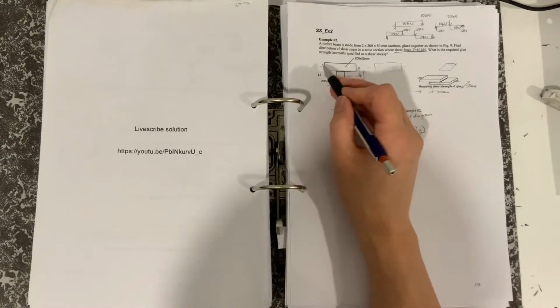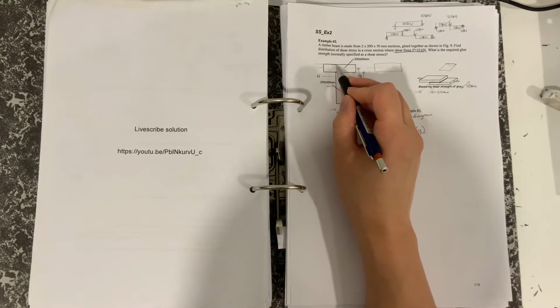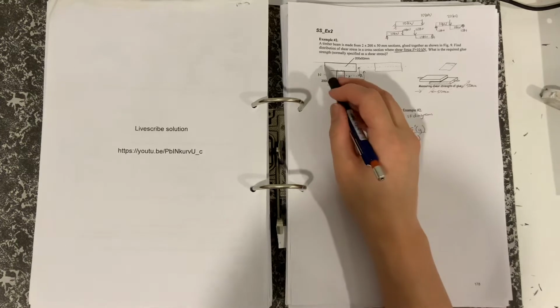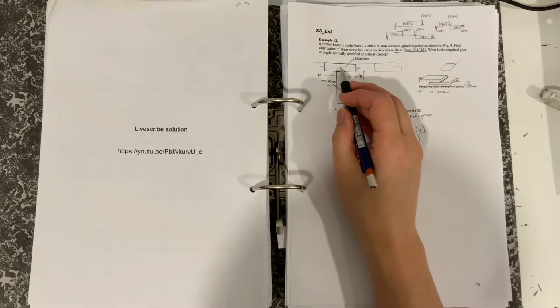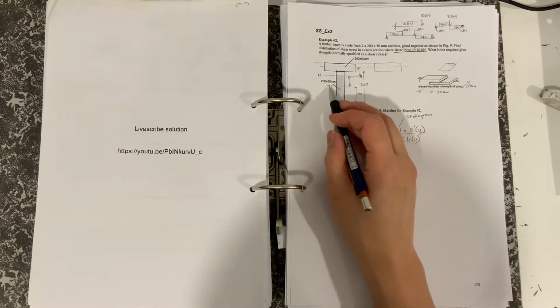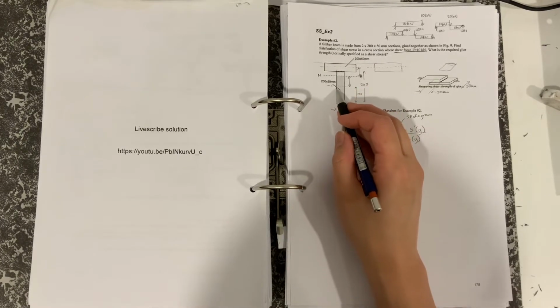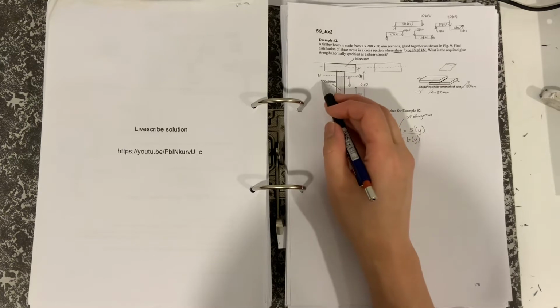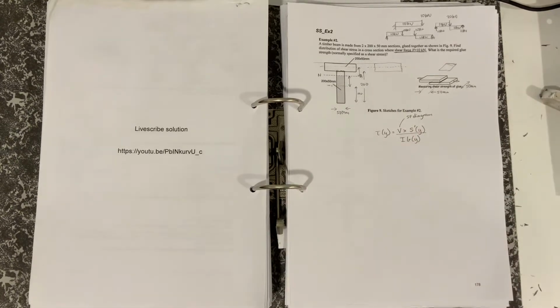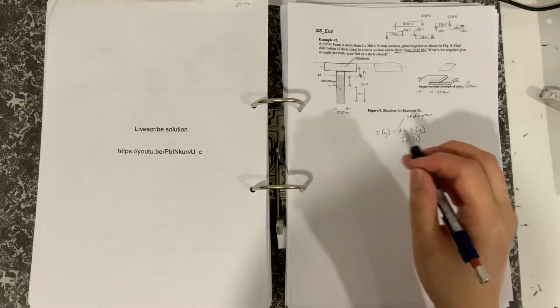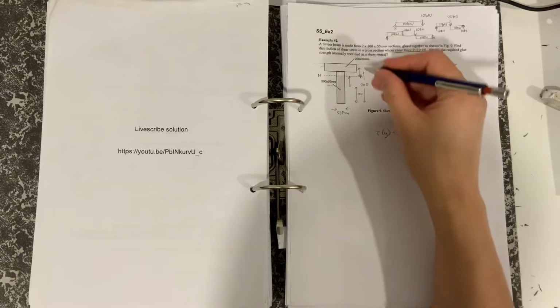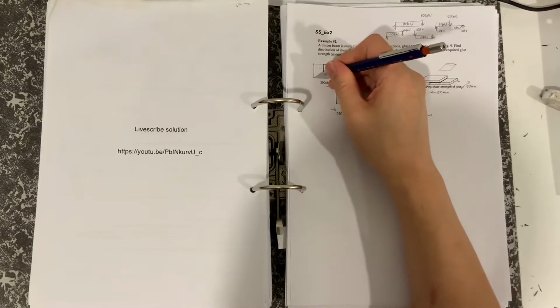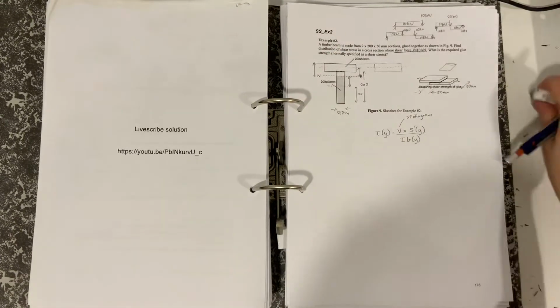I suppose you could take that as a datum point, and you could multiply that area by that distance there, and then add that multiplied by that distance there, and then divide it by the whole area. A faster way to do it, and that would give you the position of the same neutral axis, which would give you that distance there.